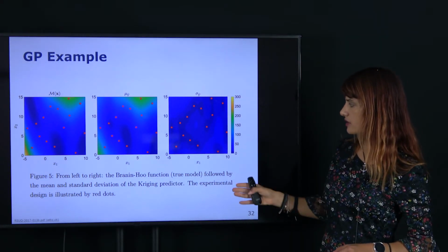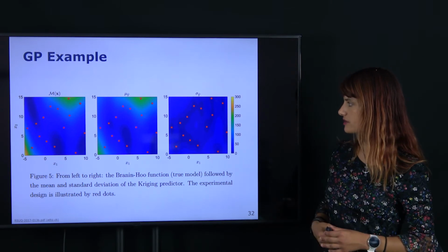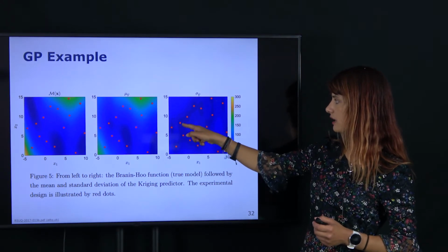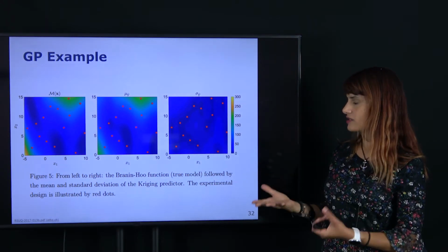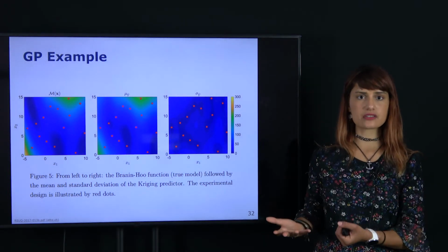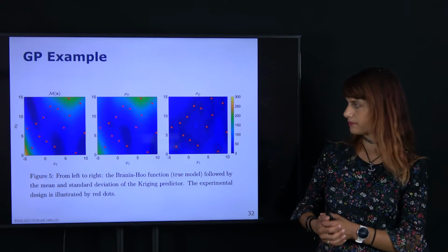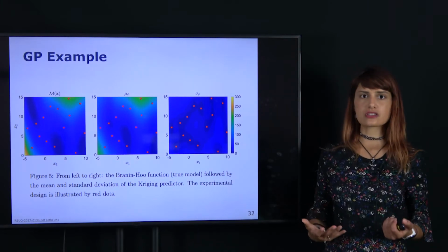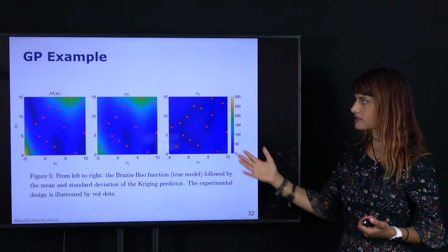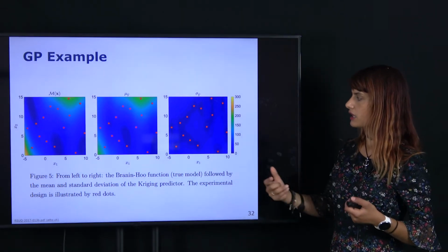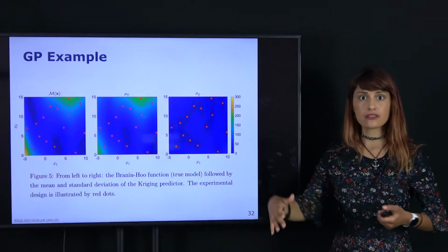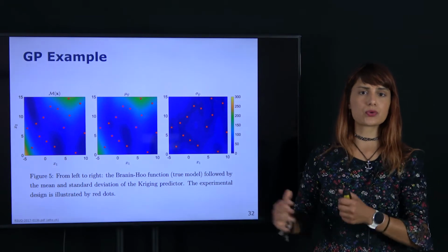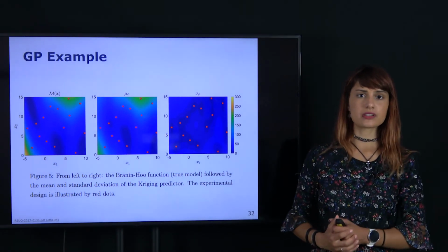And with the covariance function, here we see the variance over this 2D space, and one would expect a low variance associated with the points where we actually have training data, because these are the points that we actually measured, so we have less uncertainty here, therefore the variance is lower. And we can already start to see how informative planning would fit in such a map representation, because if we have a variance, intuitively we can start to think that if there is a location with a very high variance, we have high uncertainty there, and maybe we want to direct the robot to sense there so that we can improve the confidence of our model and achieve our informative planning objective.